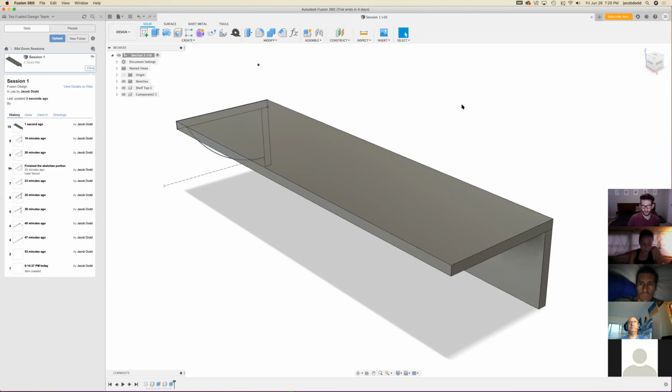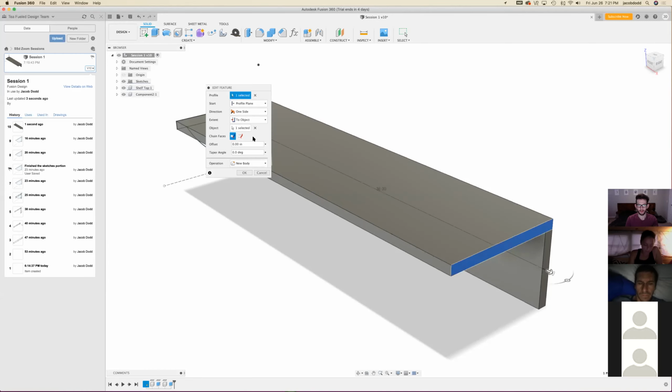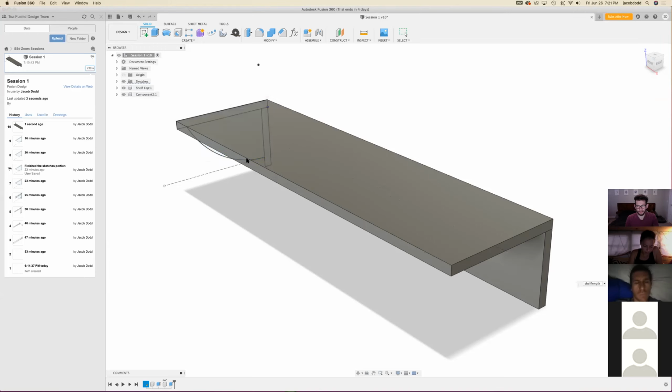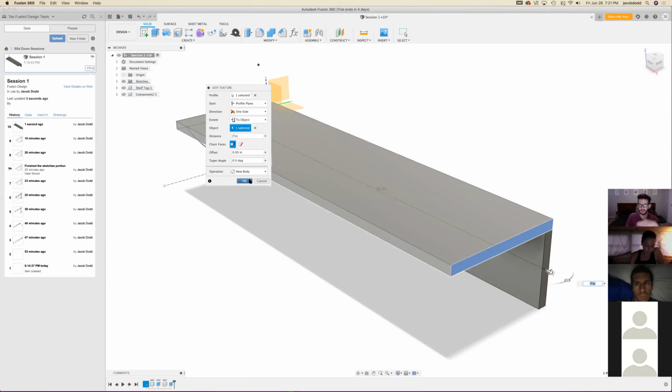Yeah, exactly. That's a great example. And I guess the one caveat is with the CAD software, if instead of doing "to object," we did distance, and then we typed in shelf length as well, because it's a computer, it's always going to get it right. It has the same effect in this case as if we did just do two. And in general, that's probably a better practice, just to use extruding to a face.